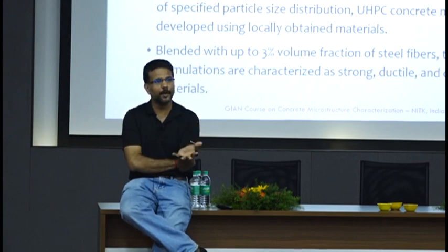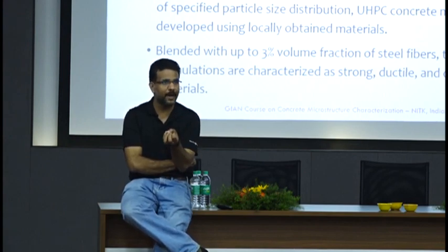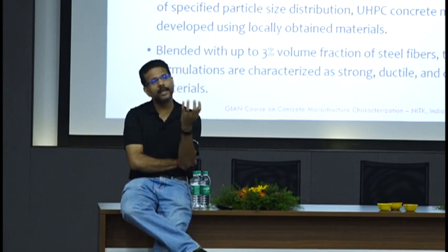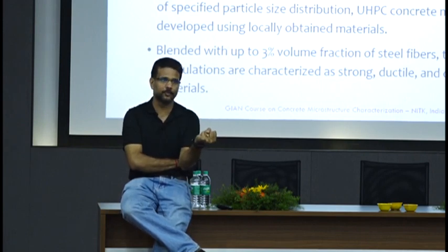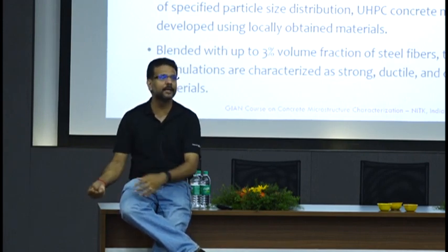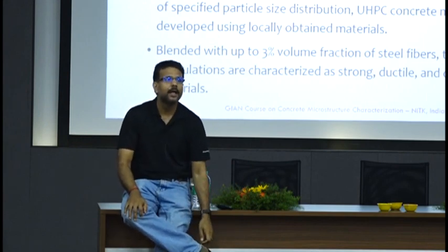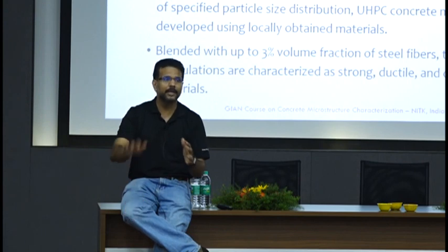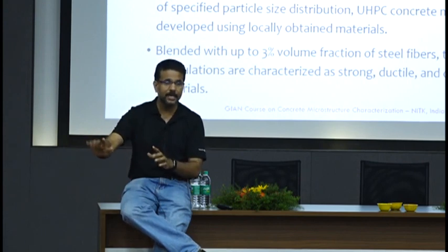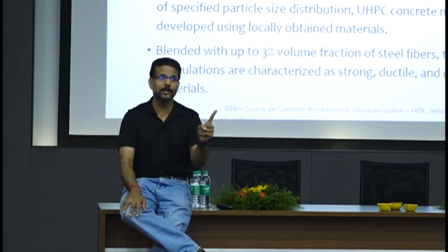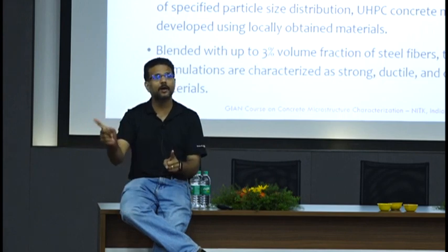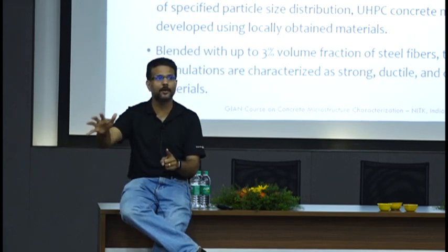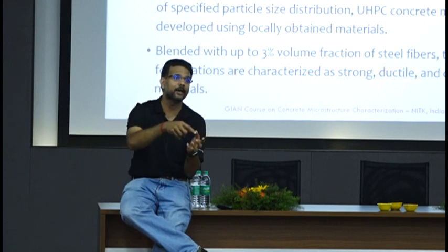is an intrinsic property of how well you have packed your microstructure. Strength comes from the physical portion, which is the packing, and the chemical portion, which is the reactivity. There is no way that you can separate the contributions of both. Your chemical part is time dependent, your physical part is really not time dependent, but when the chemical contribution changes, when you have reaction products formed in different parts, your physical packing also changes.